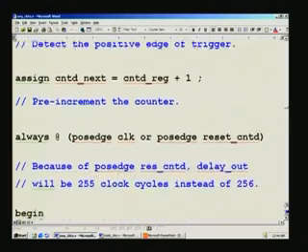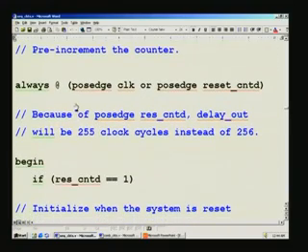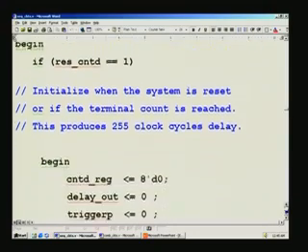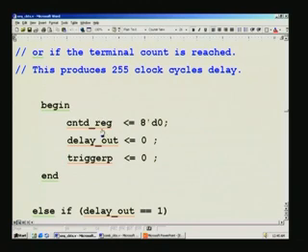And we have an always block which does the actual sequential work, namely the counting, and that is what is here. With the reset condition being satisfied, you reset the system: all these different counters, the delay output, and the internal storage for the trigger condition to store the previous status as such. That is what is here.